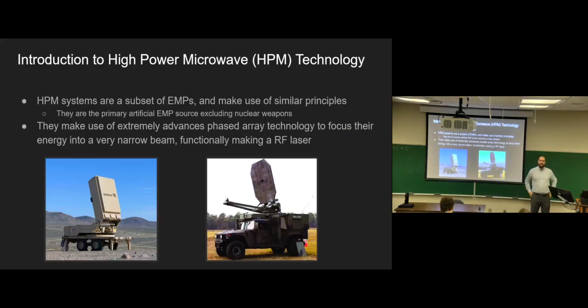Does it do that in a similar way to like a phased array radar? Yes. I will say though, it does do things similar to phased arrays, but it's not exactly an active electronically scanned array. There's a couple differences there. There are things about active electronically scanned radars that fail when you start amping the power really high. Certain components just can't handle it. Their technique, and I think I mentioned it a little later on, but the new method is to use what's called a software-defined radio. And it allows you to do some fancy stuff. I talked about it a bit later on.